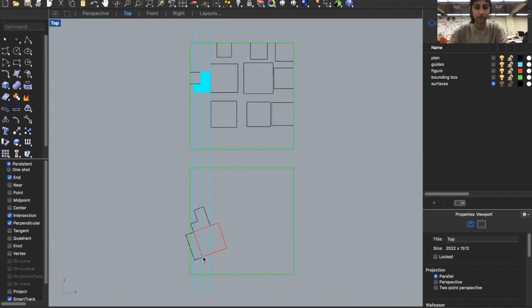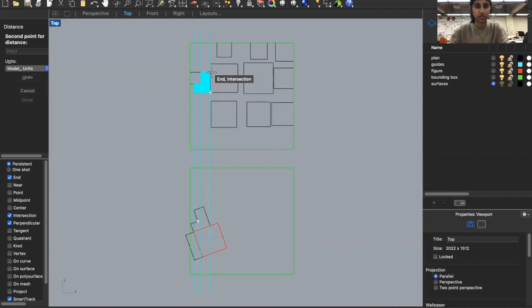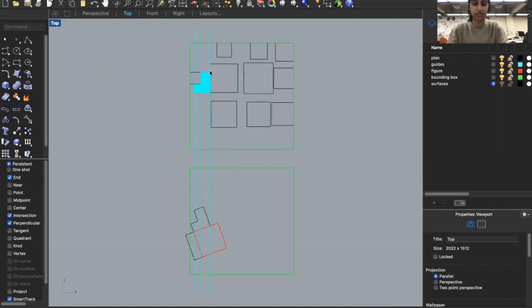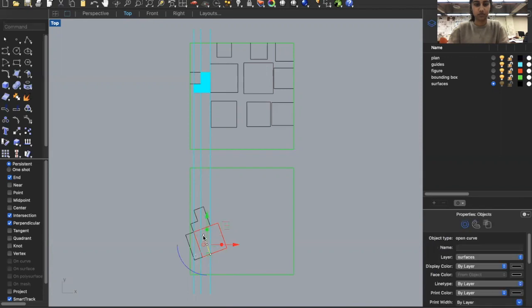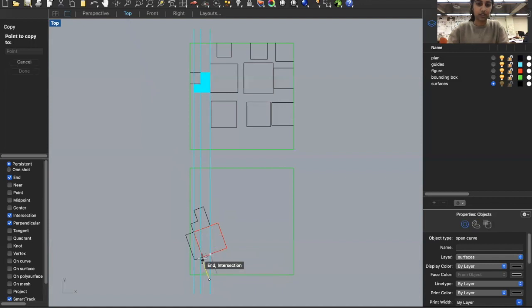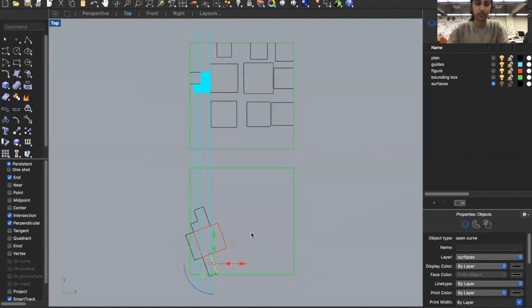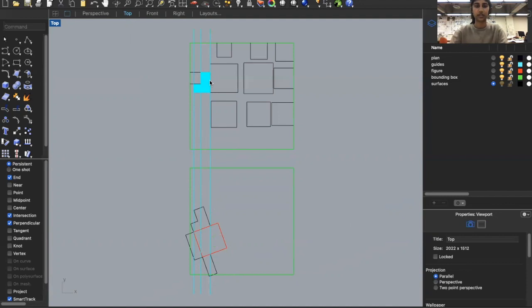And I'm going to do it one more time for this bottom surface, which would follow the depth right here. And that's going to be the distance from this point to this point, which we found earlier was 1 and 17/32 inches. So I'm going to draw a line that's perpendicular. And it's going to be the same for the entirety. So just copy that over and close that horizontal. And these are going to be the shapes that we need to cut out in order to get this figure projected in our plan at the angle.